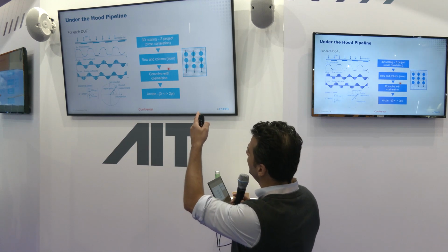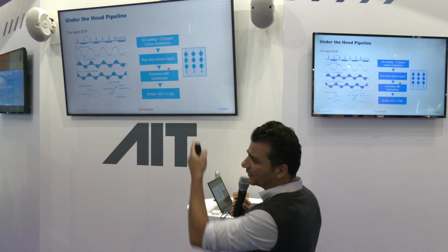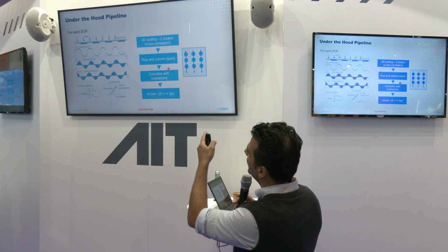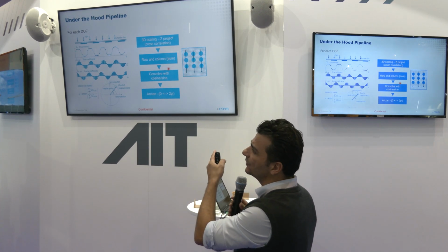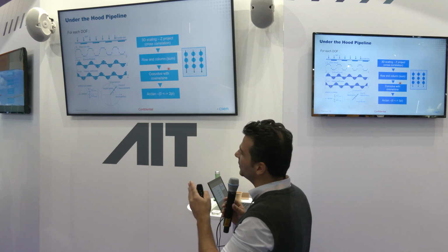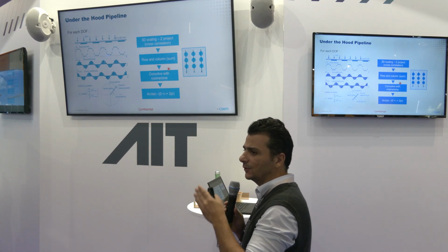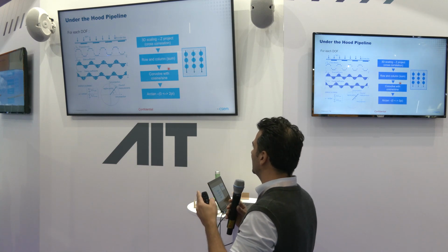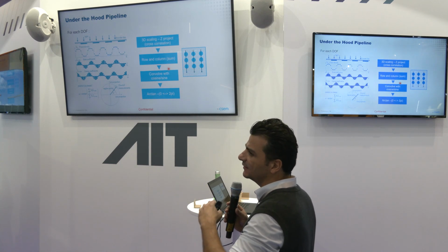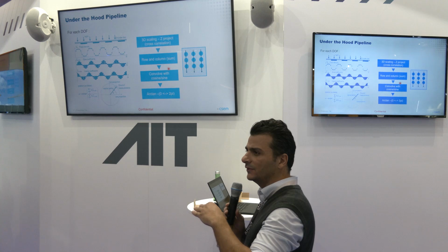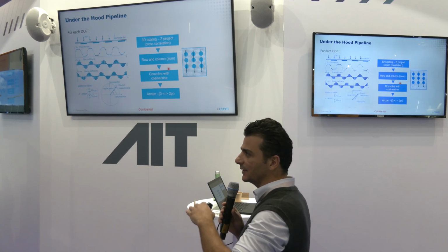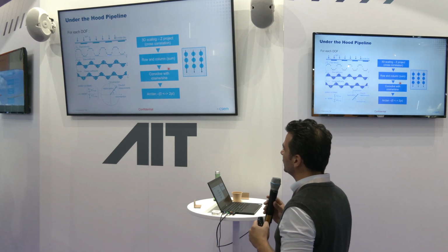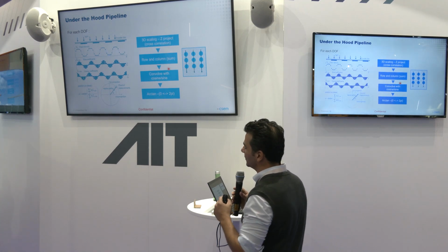When we talk about the imaging processing pipeline, it is quite simple. We have the light incident on an encoder disk or a diffraction grating. We capture the intensity of the pixels, then we sum along the rows and along the columns. Once we have that, we convolve it with a sine and cosine, and based on the angles between them we are able to get the phase measurement of the shadow image, and thereby the position of the LED source relative to the detector itself.